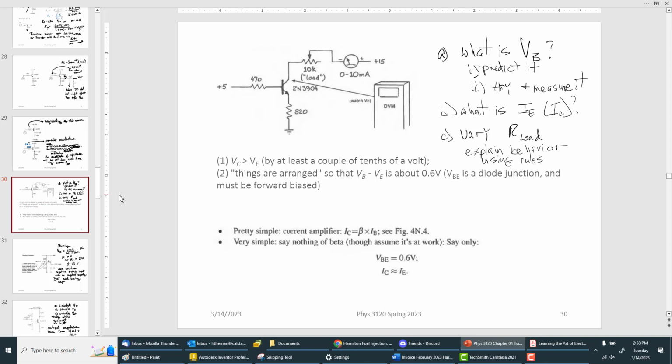So you'll need to test it. You have an ohmmeter, you have your handhelds in ohmmeter mode, or you do your plug-in voltmeter.